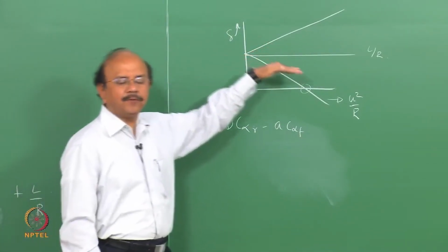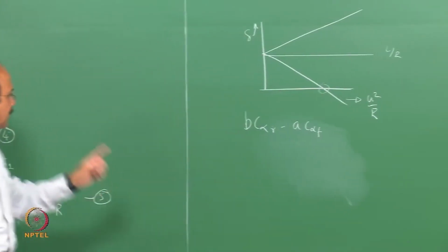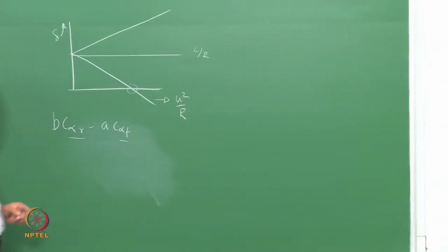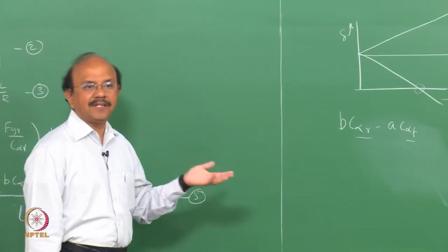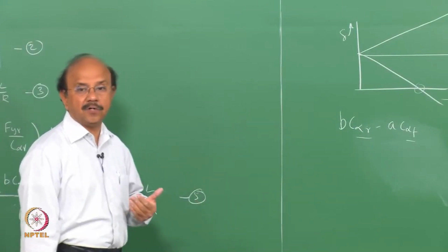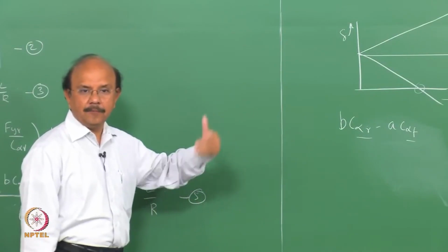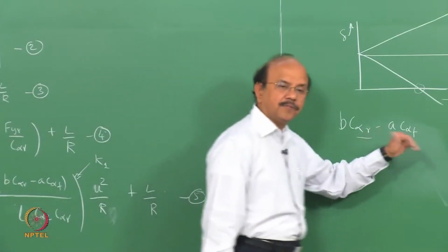Okay, why is it that people do not look at neutral steer? Basically because, look at that quantity, it is B C, alpha R and alpha F. Alpha F and alpha R, what are they? They are the lateral slip stiffness, as it is called. Okay, lateral slip, because it is lateral force versus slip angle, the slope of that curve, so lateral slip stiffness.